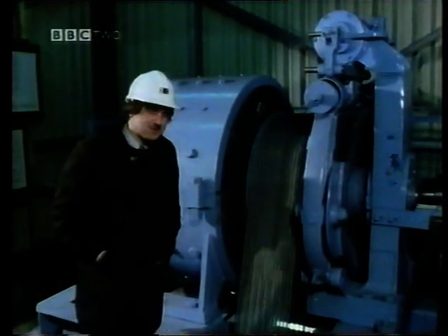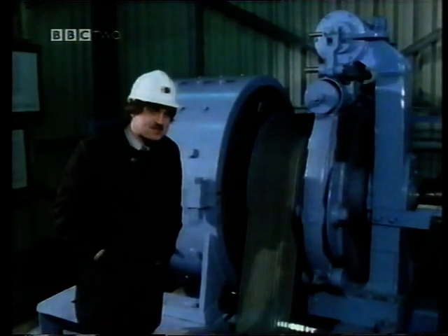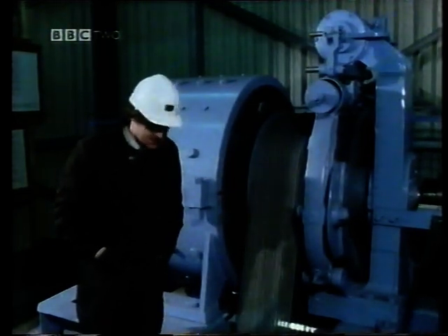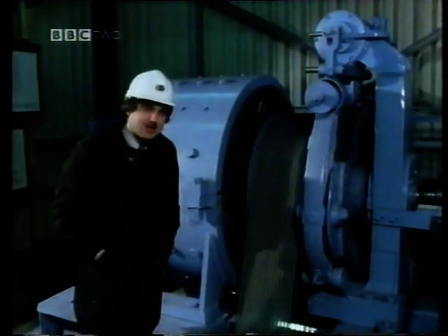Well, here's the final version of the traction lift system they designed. And we've taken down the guardrail so we can get a closer look. As you'll notice, there are 16 ropes on the winding sheave. That means 8 ropes in double wrap around an idler pulley down below. And if you remember, that's what the designers calculated to give enough traction to the system.